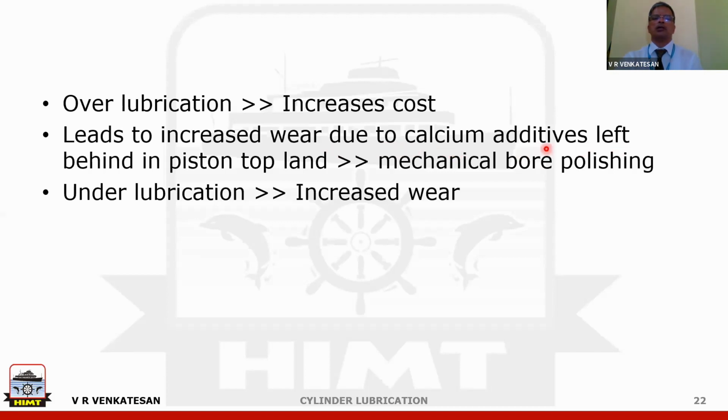Calcium, the TBN in the lube oil, comes from alkaline additives, and they are basically compounds of calcium. So these calcium additives will be left behind and they will build up around the top land, and that will lead to this mechanical bore polish.